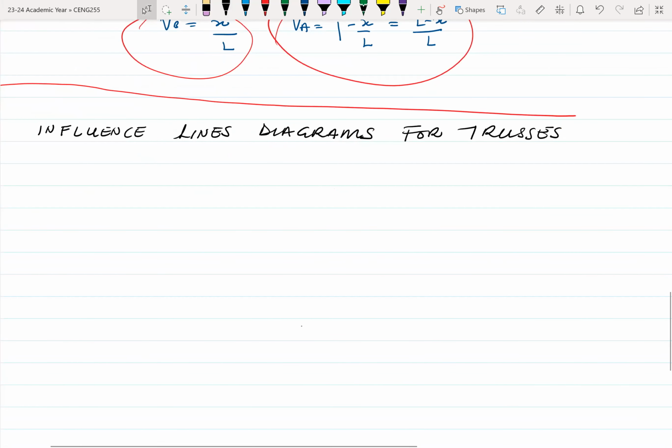So normally we call trusses pin jointed frames. The reason for such a beautiful name is that we assume the members are strictly axial members. They transfer loads through axial behavior, which means that they are not designed to resist moment. We also ensure that in our analysis, the loads are positioned in such a way that they do not cause moments in the members, or even at the joints.